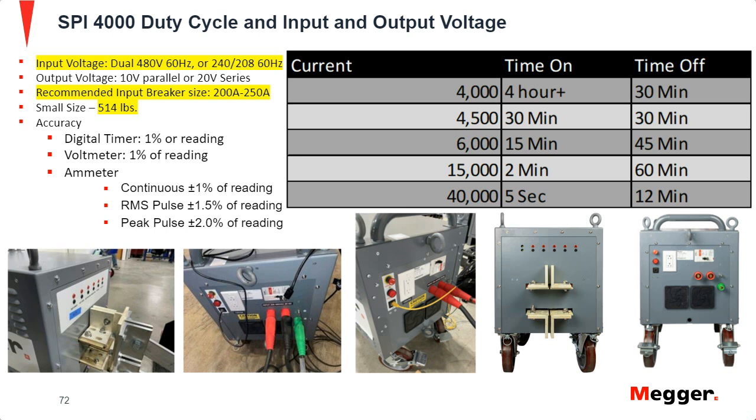The way you can do that, typically on every breaker, there's going to be a cat number. So if you type that cat number in online and you just type in datasheet after it, typically you'll be able to find a few different sites where, if you search through them, sometimes you'll find a PDF of a data sheet for that trip unit or for that breaker, and then you can find the trip curves on there. That's typically the best way to go about doing it, because a lot of times, especially with breakers that are ancient, you won't have any luck finding trip curves, but that'd be your best bet if you don't have one on hand.